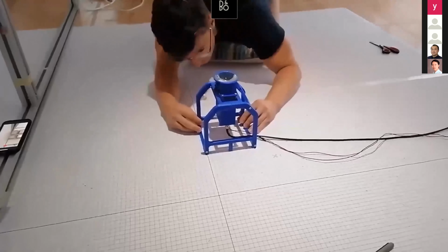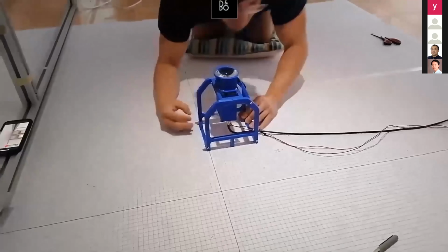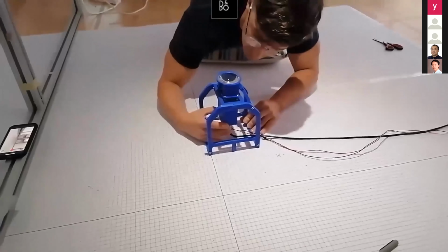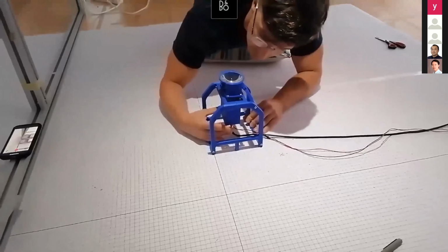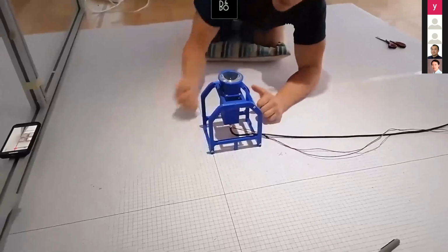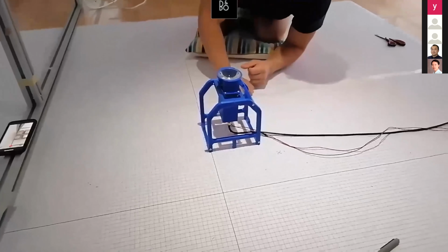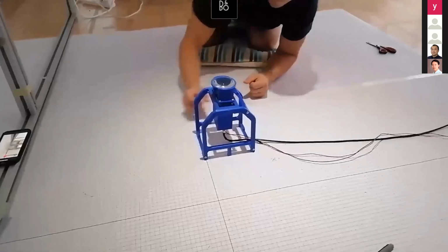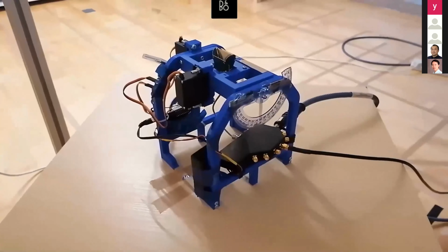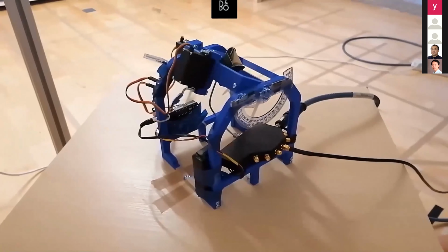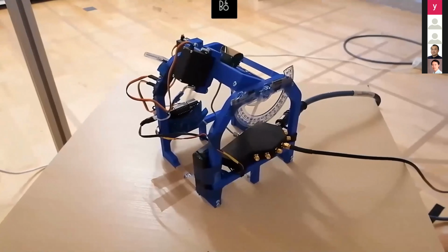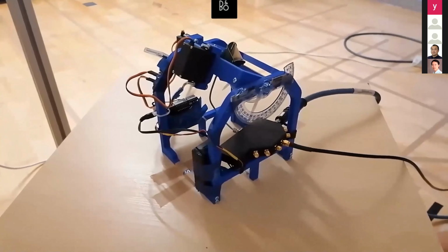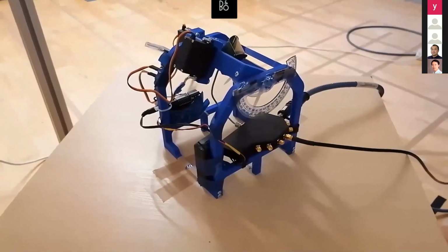Taking VLC measurements requires positioning the photodiode receiver on a grid, angling it towards a communication LED transmitter, and measuring performance on the test receiver. A 2-degree of freedom gimbal is used to rotate the VLC photodiode receiver towards the communication LED in order to maximize the received signal and hold it in a fixed position for measurement. Taking millimeter wave measurements requires choosing the transmit angle, positioning the receiver on a grid, angling it towards the transmitter, and measuring performance on the test receiver. The 2 degree of freedom gimbal was enhanced to be able to do this autonomously.